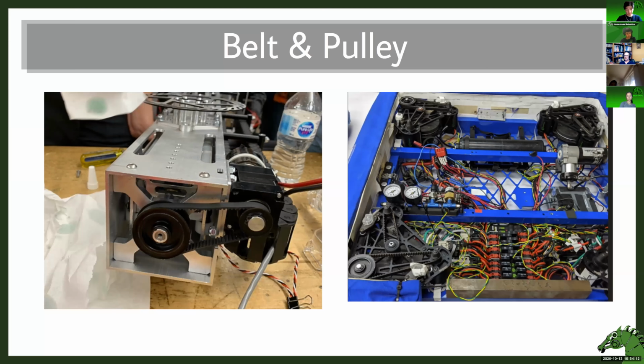And then there's something on the right here. This is a swerve drive that I talked about last week, where there are 4 separate motors in the corners, and right here it has inverted motors. You can see the motors up here inverted, but they use a belt to have the motors in a different location in relation to the shaft, but still be able to power them. And they also took advantage of the fact that they're using a belt and pulley to squeeze out some more reduction.